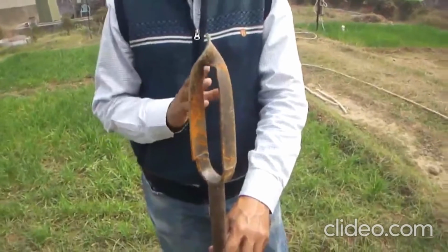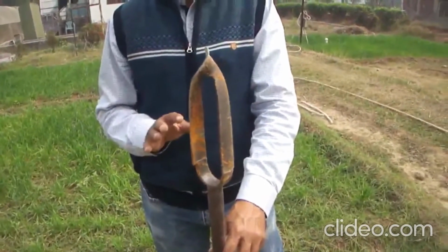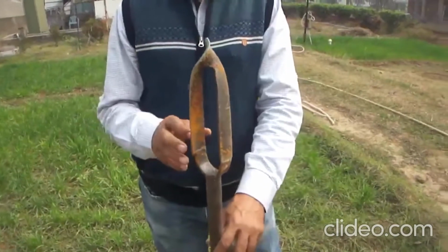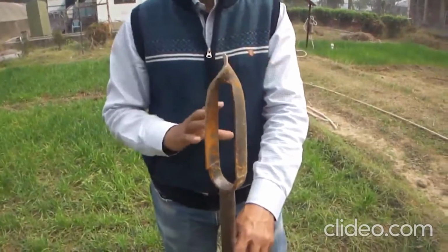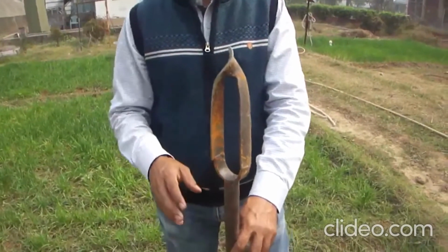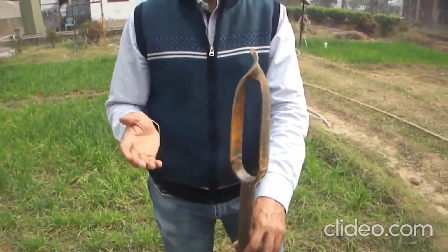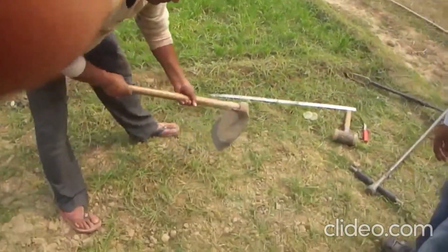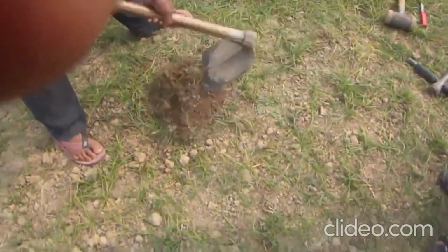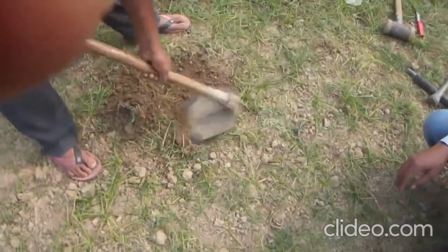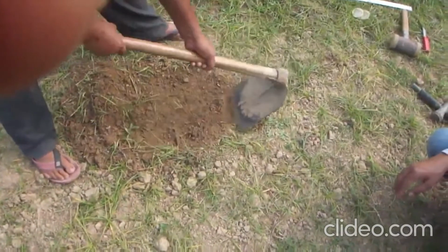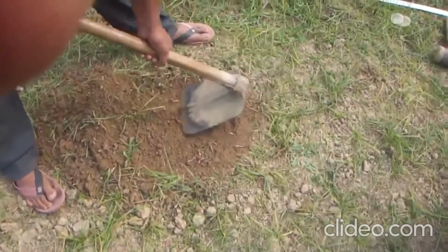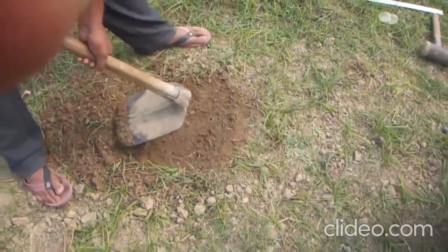So let us take two samples, one from near the surface and second say after 20 centimeters. Let us take between 20 to 25 centimeter because this core size is just 5 centimeter. Let us see first the top surface and then the deeper layer sample collection. First we are clearing the soil up to say 5 centimeter. Just clear it, make it a level surface so that your sample is level, and then use this core sampler.